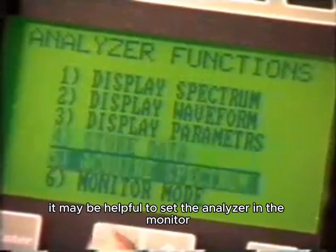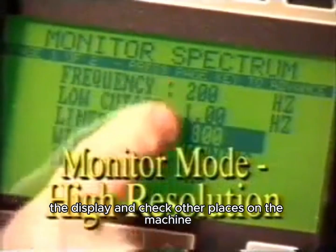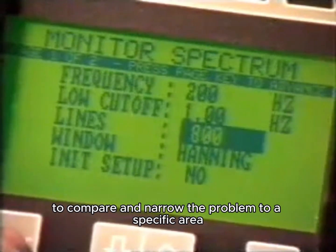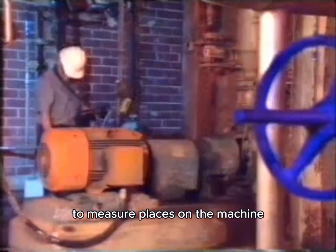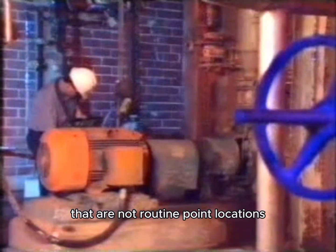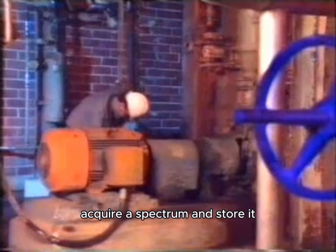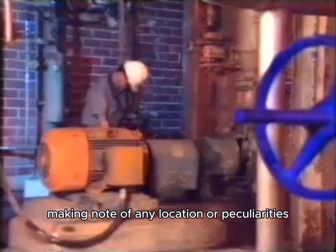It may be helpful to set the analyzer in the monitor mode to continuously update the display and check other places on the machine to compare and narrow the problem to a specific area. Use this monitoring mode to measure places on the machine that are not routine point locations. If a problem area is detected, acquire a spectrum and store it, making note of any location or peculiarities.